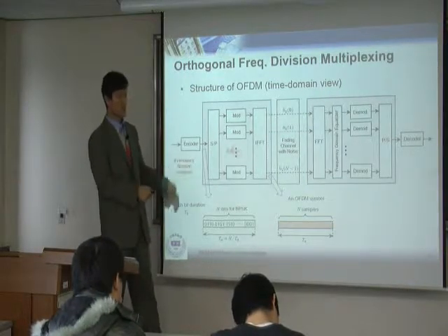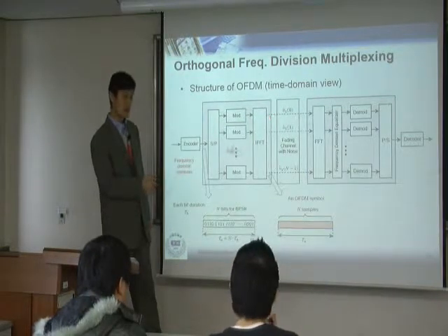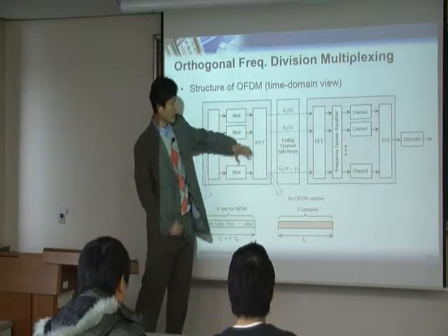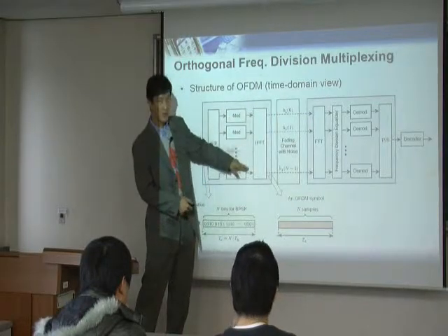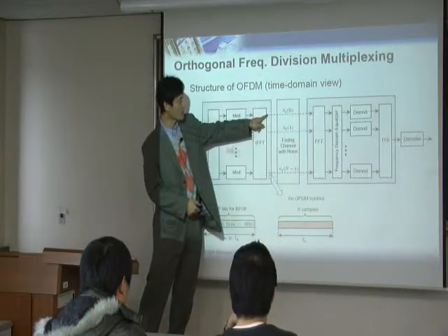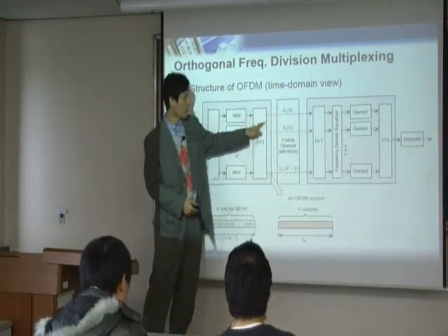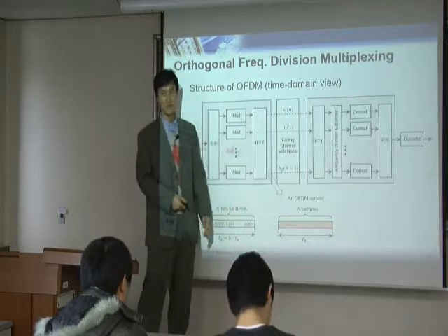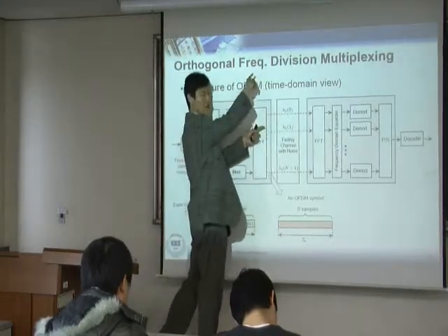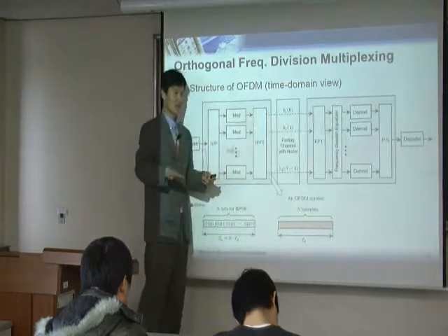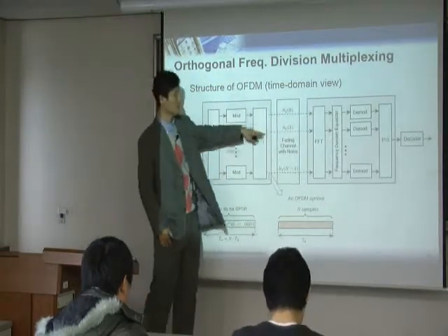Well, of course, you probably don't have an impulse because this is a discrete system. What you have actually is that since you have n different subcarriers, if you have all 1, then the first one you get is n, the summation of all this, n. All the others are 0. Okay? So if you think about that, this is n, so big. All the others are 0, nothing. So think about the power difference between this one and this one.